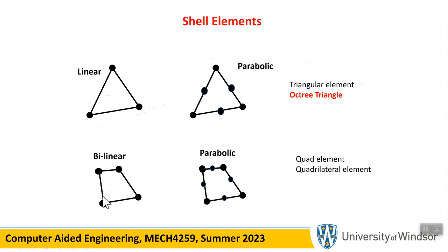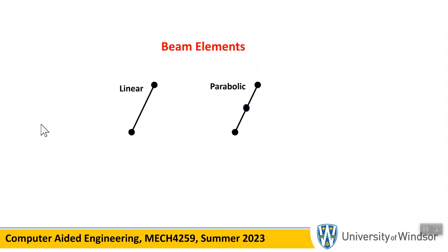Same thing here. If an angle is very close to 0, which automatically means another angle is going to be very close to pi, this is going to be a highly distorted, very skewed kind of shape. Visualize it. These are called distorted elements, and they are bad. So that's what we mean by distorted element that can cause a problem.